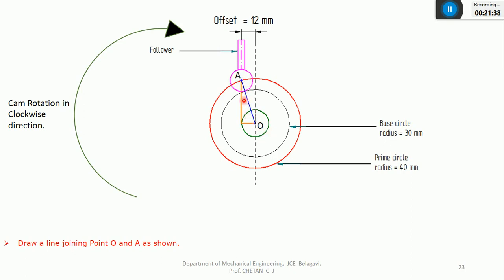And I'll indicate the 180 degree. First 180, there is no dwell at all. I'll directly go to the return stroke, that is 180. It covers a total of 360. It means only 2 angles, because both the dwell angles are 0. Only the outstroke is 180, return stroke is 180, total 360. So this is the outstroke, that you can indicate as AOB.